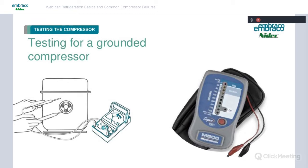Just connect one lead to the terminal and one lead to an unpainted surface of the compressor body. Hit the button and look at the LEDs. It's going to give you red, yellow, green, yellow, or red at a certain, below a certain megohm reading. You might have a compressor that's still running, but you might read it and it might be in the yellow. It could even almost show red and still be running.